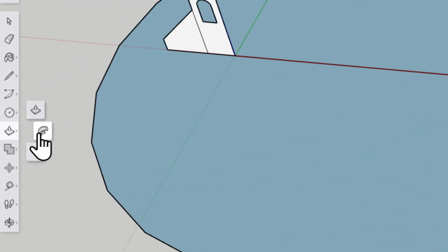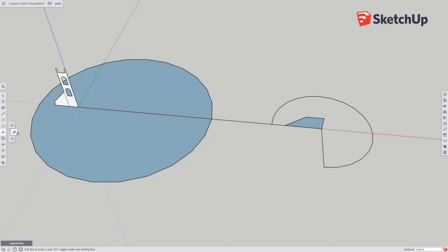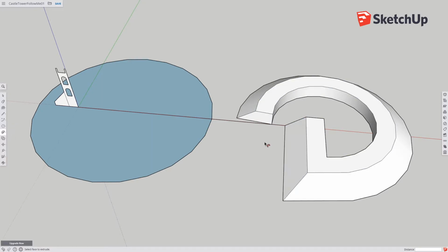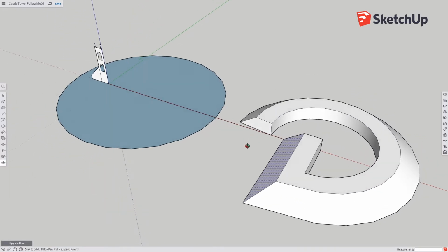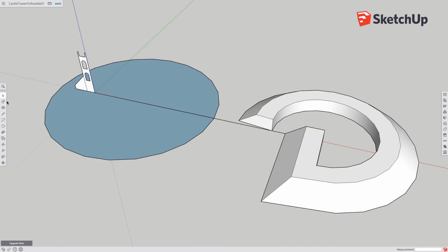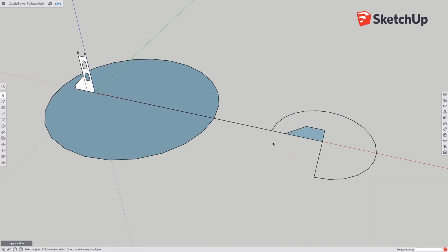So this is what we're going to be looking at, that Follow Me tool. So I'll change that. Select, I'll take this line and I'll follow me around there, and you watch what happens. Follow me. It looks cool, but it's not what I wanted. Control Z. So what it's done is it's followed this line around here, around there, up there. I don't want that. I want to get rid of that. And I might even get rid of this because it might get in our way.